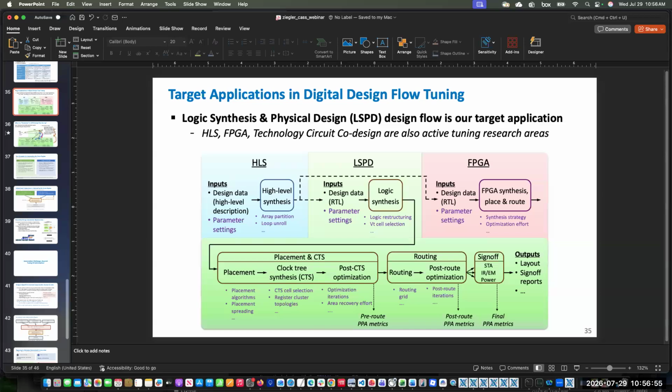So, there have been papers published on this from multiple companies and groups. I think the idea is that the options and parameters within the technology space simply manifest themselves as tuning parameters. Whereas typically you're tuning a design based on CAD tool parameters or other flow script parameters, you could imagine components of the PDK, maybe the track cell spacing or the various metal widths or whatever with your technology.